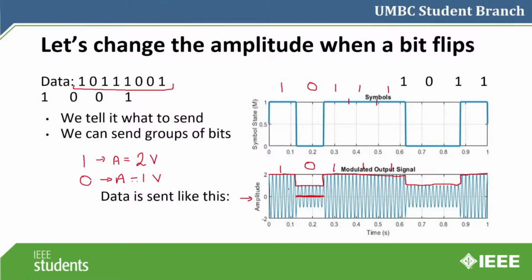And we don't want that, because there's no way to determine which one we're getting. Have we lost connection? Are we not receiving a signal? Or are we receiving a 0 bit? So instead, we'll use some non-zero amplitude. That way we know that we are always receiving the signal because we're getting something.